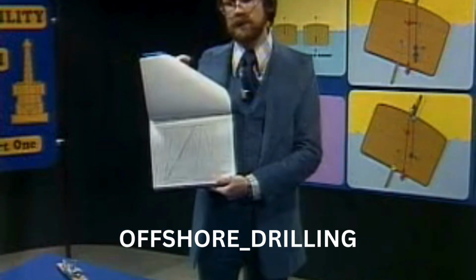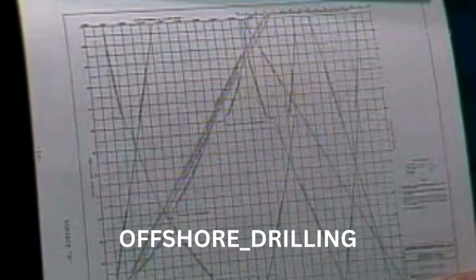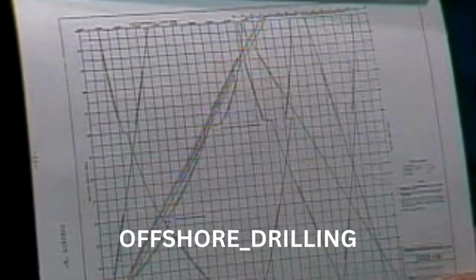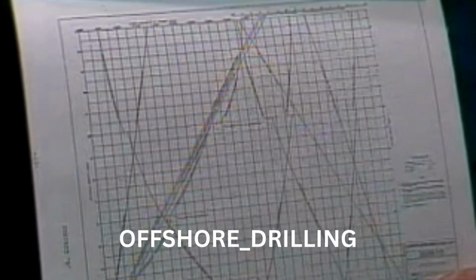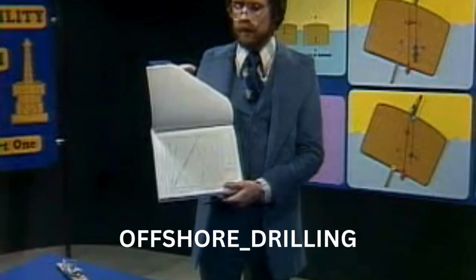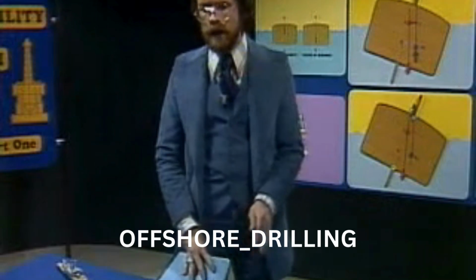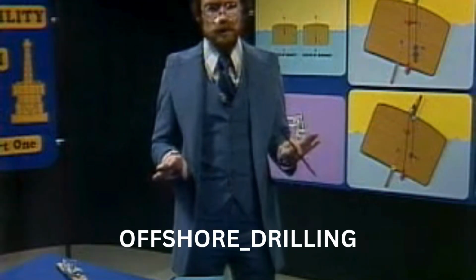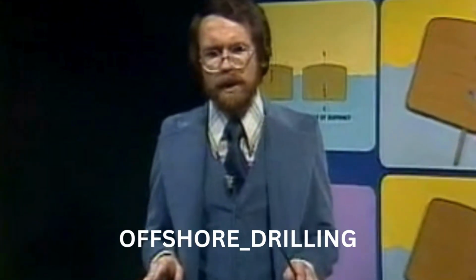As you learned in the study guide, the hydrostatic curves are a series of curves in the form of a graph which set forth the value of certain properties of a vessel involving the underwater form of that particular vessel. We will learn how to use the hydrostatic curves in the next program. For now, just remember that you will have to use the hydrostatic curves in order to locate M.